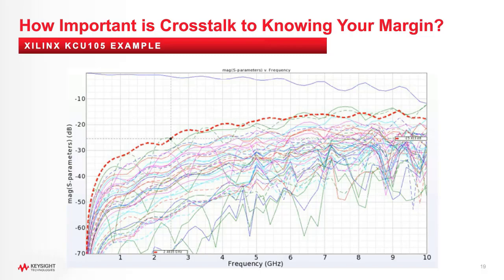So the definition of near-end for me is all of the other data lines that started on the same IC, and then also plotted far-end crosstalk, which is all of the neighboring data lines that ended up on the same IC together, and looking for the ones which had the high flyers. Now, when we come to actually running the DDR bus simulation and move to